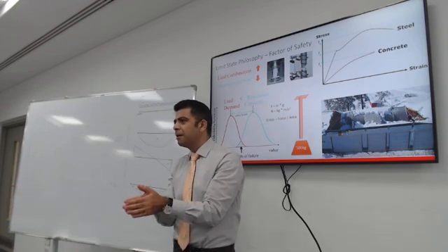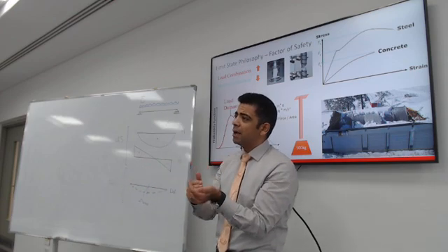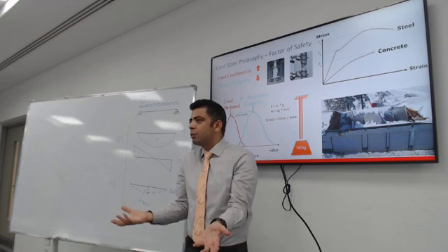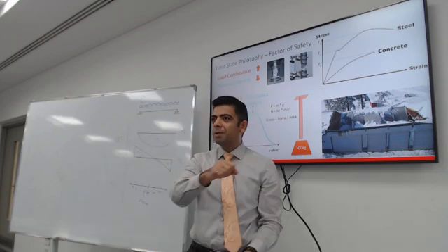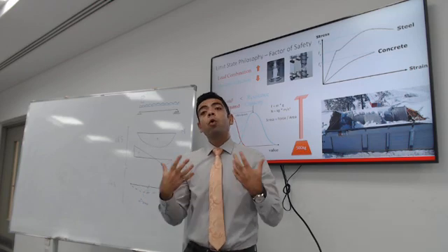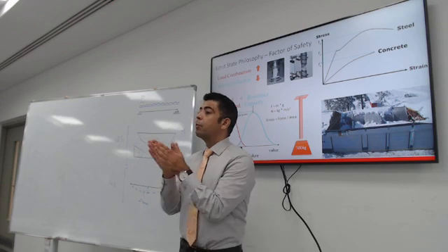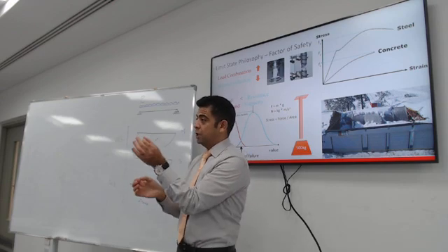Do you know what I'm saying? Well, what is concrete made out of? Sand, water, cement, and we're humans, right? You shovel the sand and put it in the mixer, or you use a more precise way in order to have some quality control on your product. The better your quality control is, the more consistently your cubes will achieve the 35.